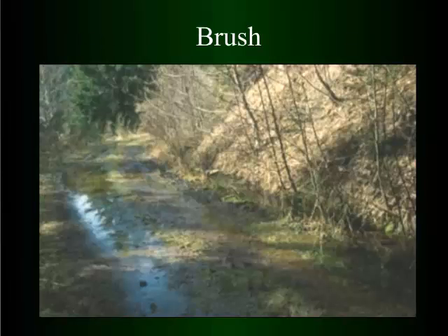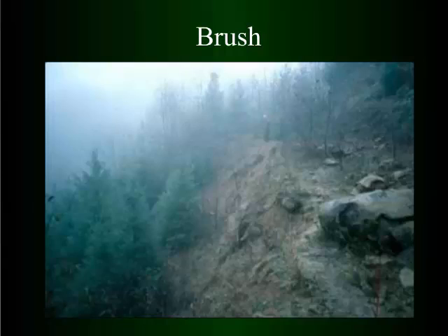This slide's a little fuzzy, but when you're talking about the condition of the road, actually in Utah, brush isn't as much of a problem as it is in some other states. But you get the roadside brush in here, and a lot of times your best running surface is this area here, and out on the shoulder it's kind of soft. Well, the brush just keeps forcing people out, and finally they get out and start knocking your shoulder off. So either you want to close the road or you actually want to maintain it, keeping people on your primary running surface.